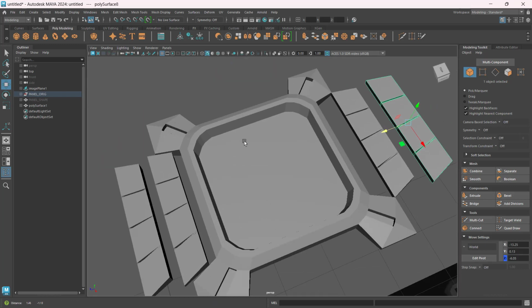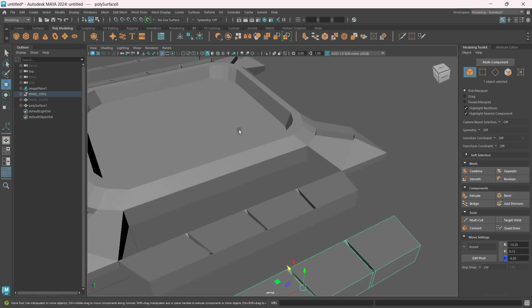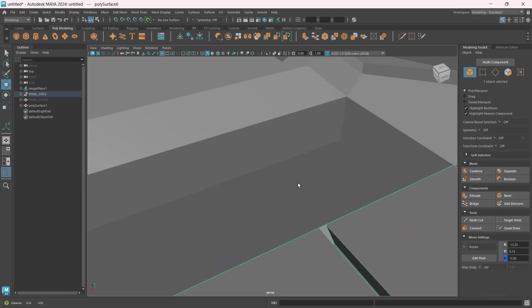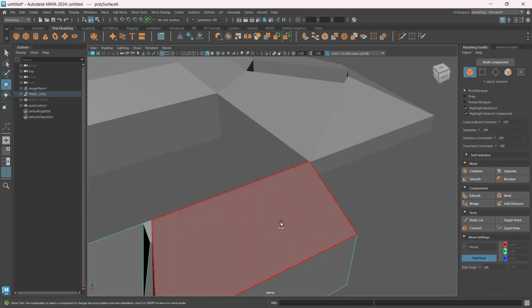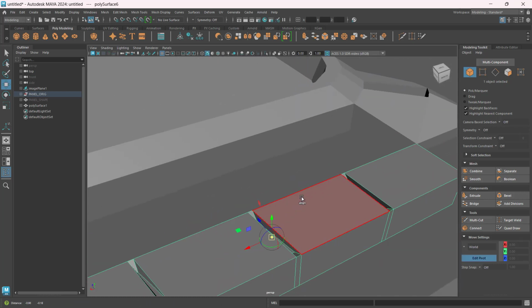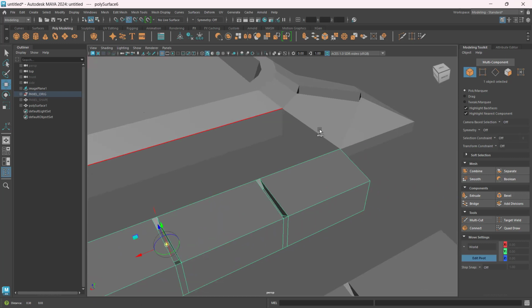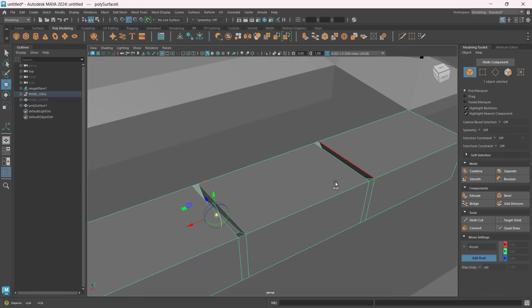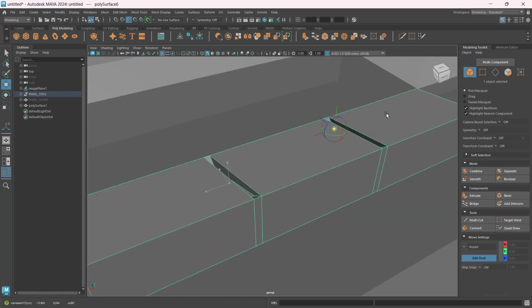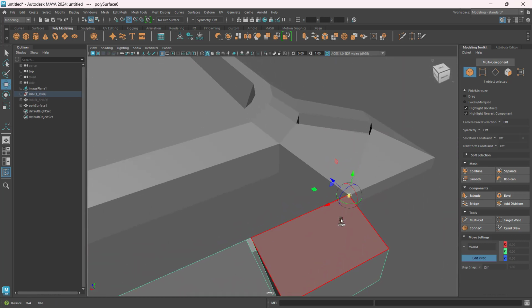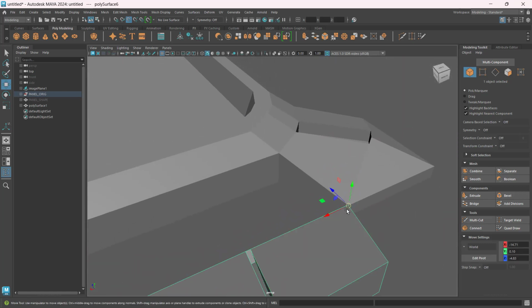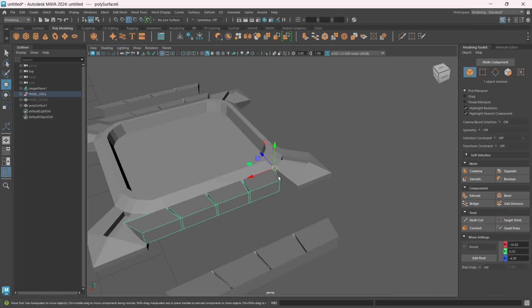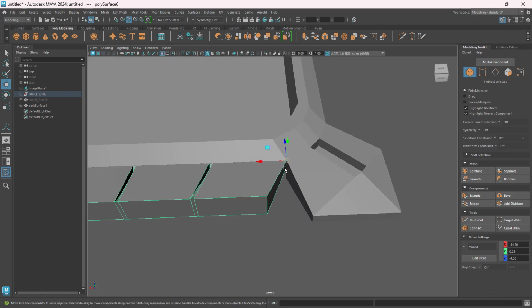So let's say I will just position this precisely just by pressing D and then turning on that snap, and then setting the snap onto a corner vertex, pressing D, and then just dragging it there onto that corner.